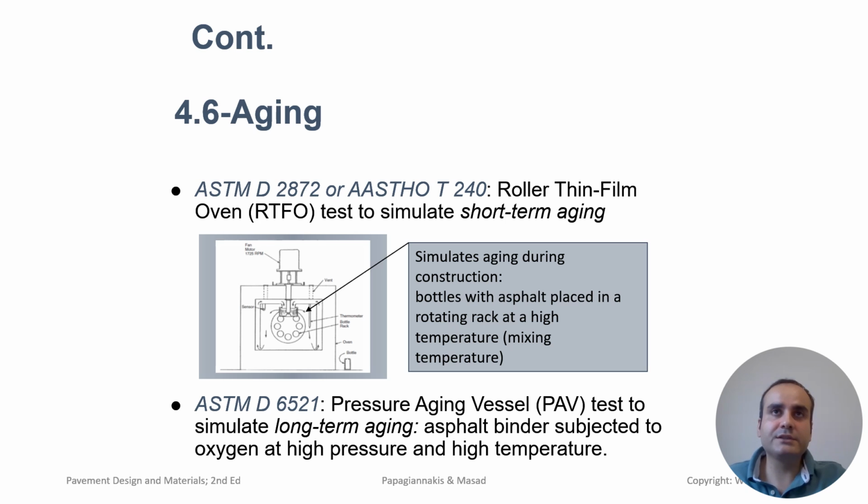Oxidation is another change during the aging of an asphalt binder. Prolonged exposure to air leads to the oxidation of the binder, which increases its polarity and molecular associations, further contributing to hardening and loss of elasticity. These changes highlight the importance of selecting binders that can withstand aging while maintaining sufficient flexibility to resist cracking.